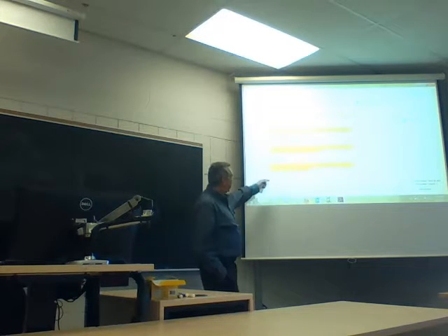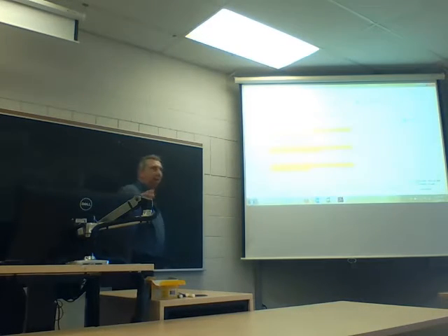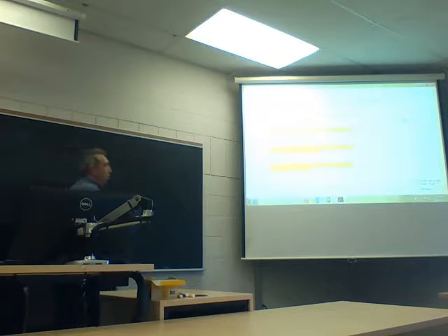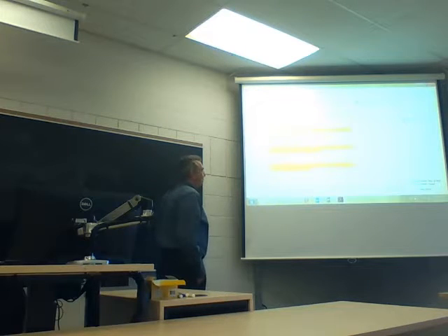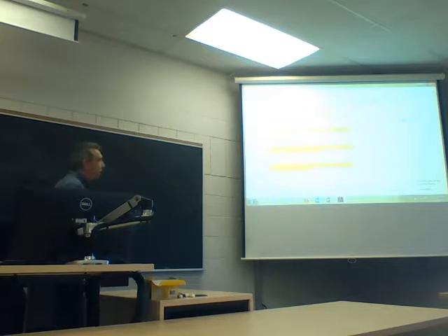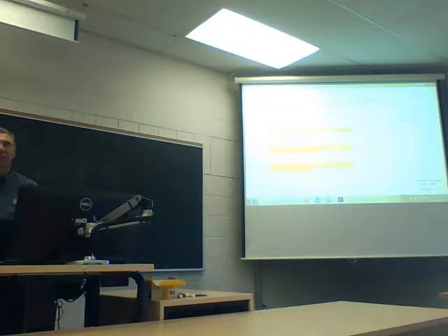Spiral valve. Spiral valve we probably have not heard of too much. A spiral valve is used to open and close bypass ports in the stator, which in turn varies the volume of the compressed air produced. This actually returns air to the suction rather than compressing it. So it basically reroutes or short circuits the compressor, so it'll just rotate around and around.